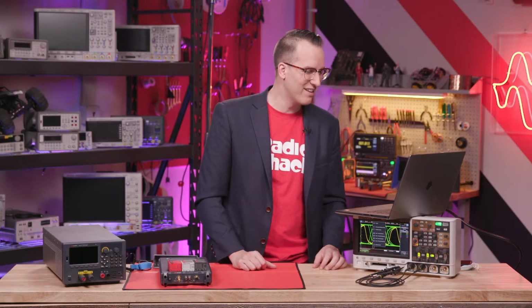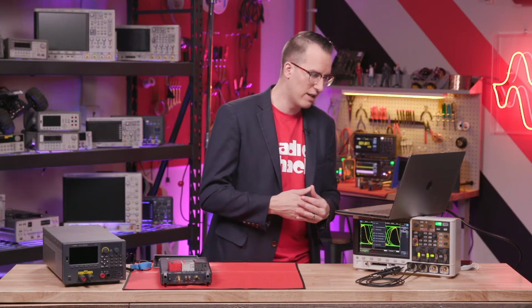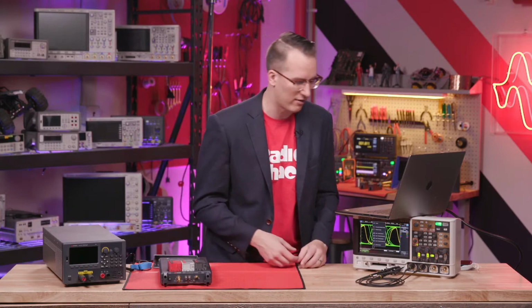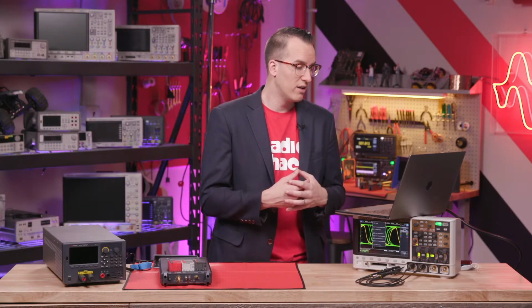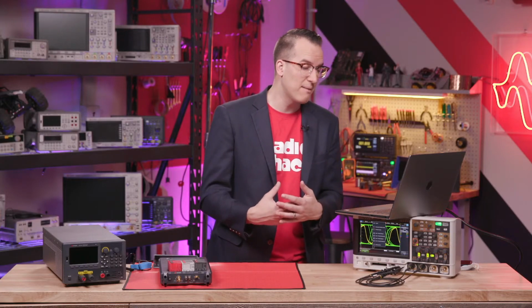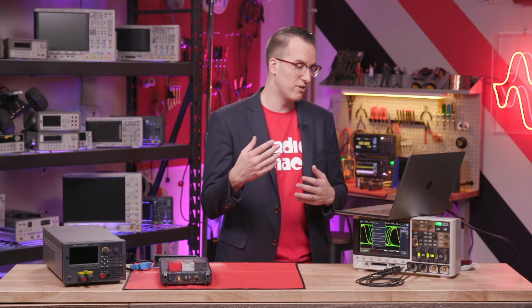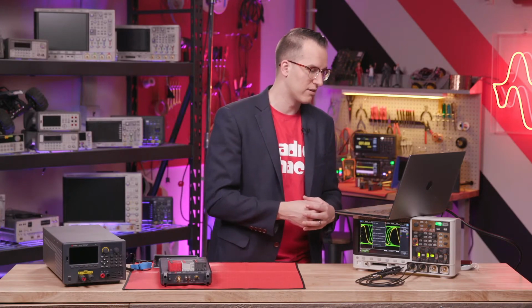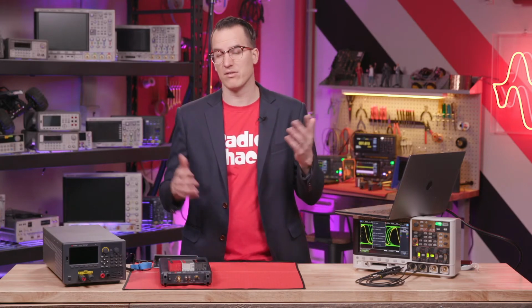Someone asked about measuring the SNR, the signal to noise ratio of an antenna. They said, can I basically measure SNR with a VNA? Joel said, you will also need a source to generate a reference signal for SNR, but you can measure it directly with the PNA-X and the noise figure app. You can measure G/T directly, which maps to signal to noise ratio. So yes, you can. You also need a good source, which makes sense if you're doing signal to noise ratio.